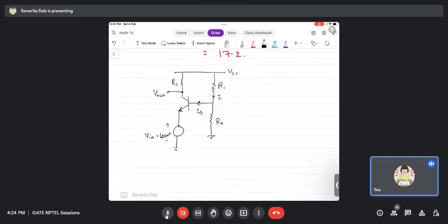Here we know that if this is VB, then VB is R2 by R1 plus R2 into VCC, right? Now you have VB and VCC.